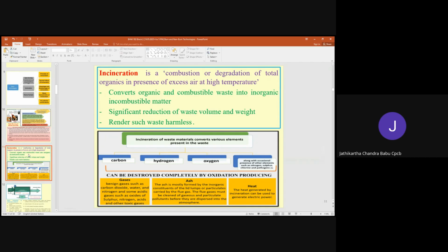After treatment of waste, we are going to get only the ash, and whatever emissions are generated we are going to control through air pollution control devices. We are also going to generate some liquid waste, and the liquid waste is treated. In the process of treatment of liquid waste, we generate effluent treatment plant sludge. We call it ETP sludge. That is also hazardous in nature. Therefore, that waste also has to be disposed of through landfills.